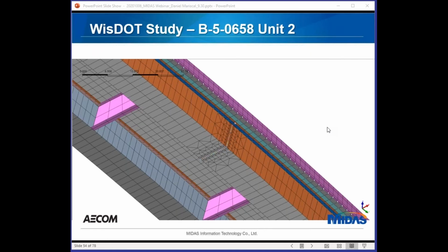So we started by removing the spring at the middle, and we worked our way out towards the webs from either side. When we got to the webs, we removed the springs from the webs one by one until we got to the top. So it was a progressive failure. It wasn't a one-step failure.